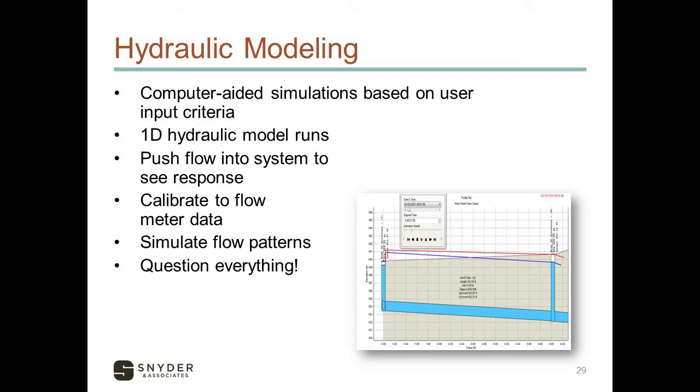Jumping into why we use hydraulic models and what are they? Hydraulic modeling is a computer-aided simulation based on user input criteria. We're pushing flow into the system, seeing how it will respond. And again, one of the benefits of having a hydraulic model, we can simulate flow patterns at a click of a button and it really allows us to evaluate a large amount of data in a small amount of time.